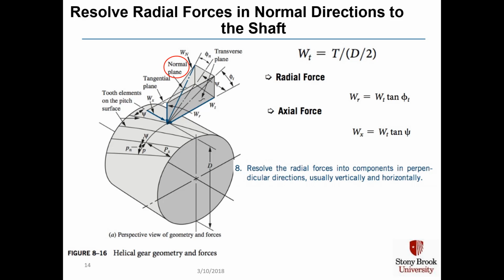The key issue here is you had better understand what all these angles are before you start calculating radial force and axial force. The tangential one is the only easy one to calculate because that's just the torque over the radius of the helical gear.